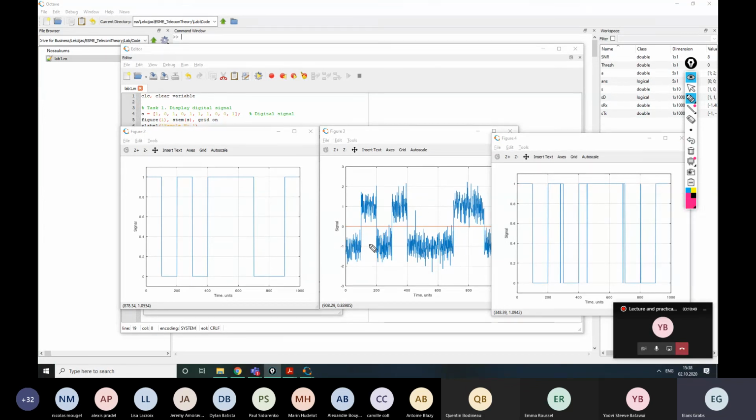Because of that, we need some averaging procedure to account for this random process. Any type of averaging smooths out that randomness. Any constant component after averaging remains the same. Any spikes and very rare events are averaged down to 0. So basically the solution would be to perform the averaging of this signal before actually comparing it to the threshold. We will speak of this most probably next time.